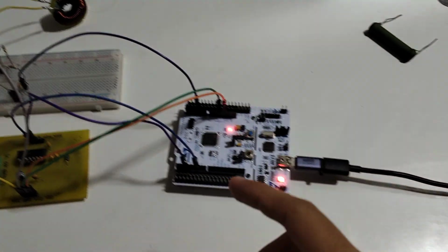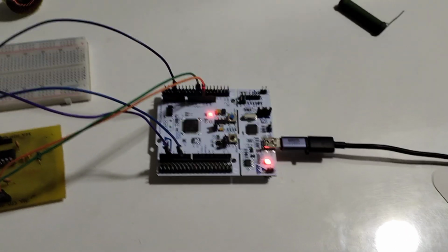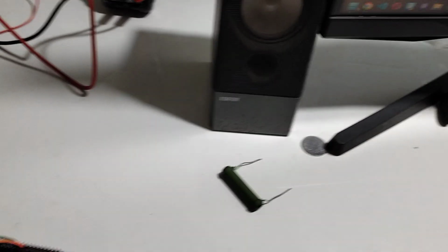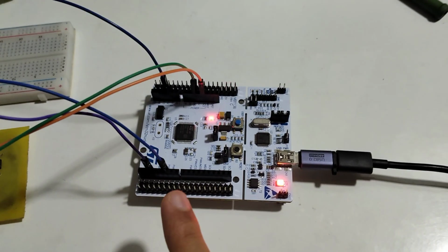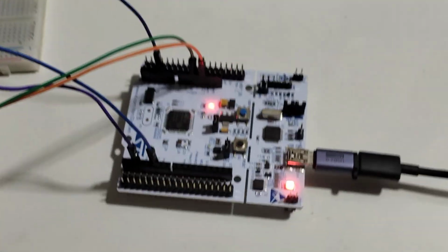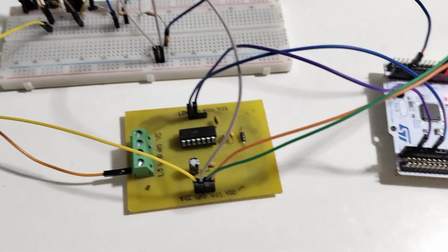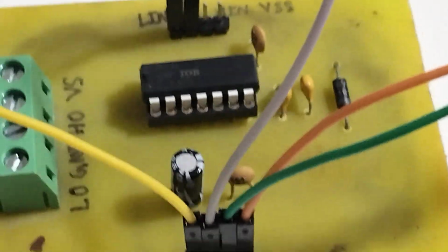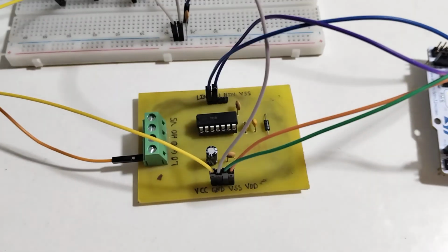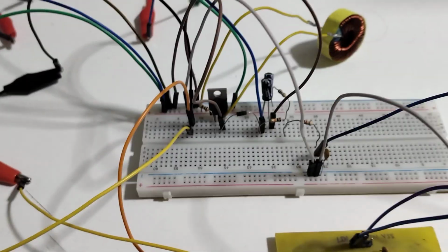Okay, so moving to the hardware circuit, this is the microcontroller, and especially the board itself, not the raw microcontroller. This is the Nucleo F446 board, same as our MSP board. So there are the pins which are going, and this is the driver, the same IR2110 driver, which is nice. It can drive both high and low side, but now we're just going to be using it for low side. And there's the power circuit.